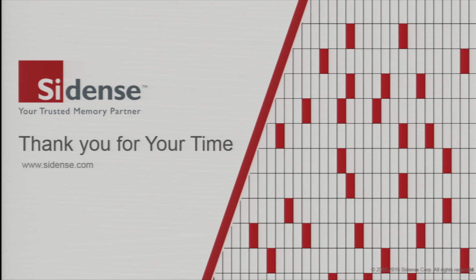The second question is, can 1T OTP work with FinFET transistors? Yes. I just got back from the TSMC symposiums last week, and FinFET was definitely a topic for discussion. So the answer is yes. 1T OTP scales exceptionally well to FinFET processes. In fact, it uses the same bit cell design that we use in all of our OTP products, so it's well understood and well known.